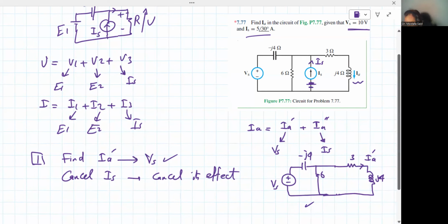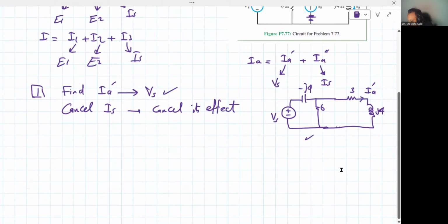Okay, so we're gonna solve this circuit now. The best way to solve it is basically using, we can use maybe the node analysis. On the node analysis, we look at the nodes with 3 branches or more. We have 2 nodes here. This node here, the first one has 3 branches, and this node as well has also 3 branches. We make one of them ground. You can choose the top one or the bottom one. Usually we do the bottom for some reason. Right? Maybe because the ground is like under us any time. So we're gonna ground the second one. And let's call this VA, for example.